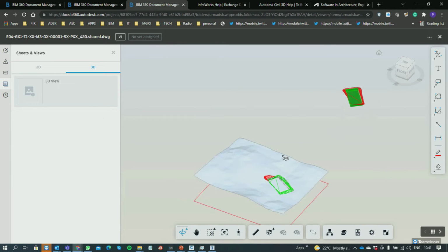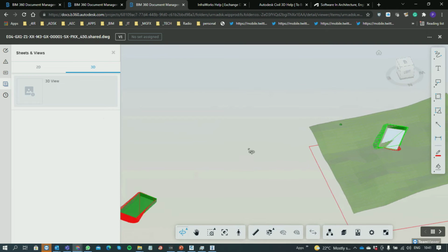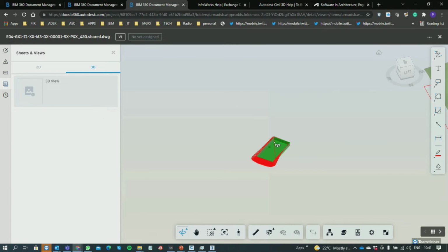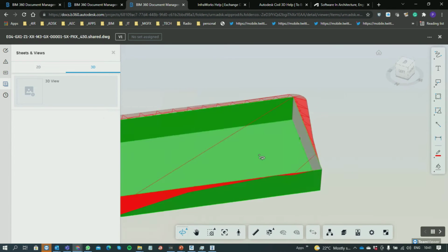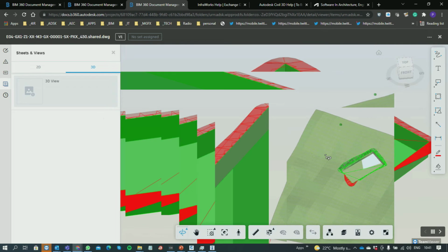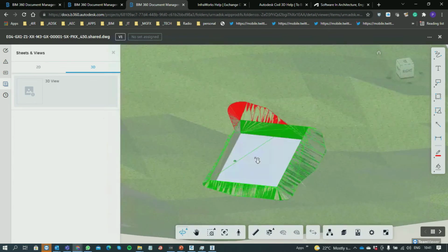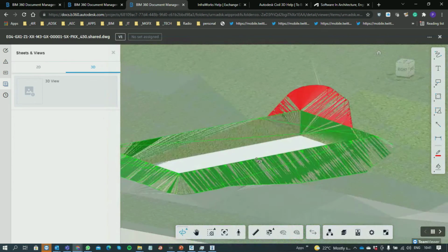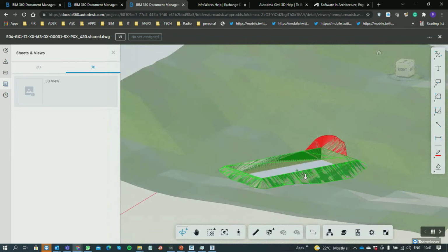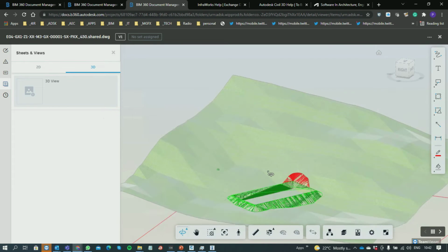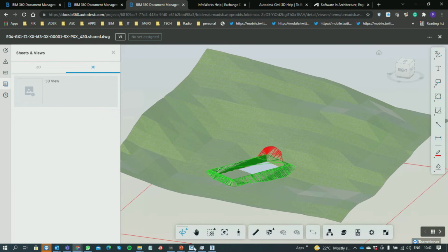Here you can see the surface that was brought out. I've unfortunately included the other surfaces, grading. So that would be a typical grading preparation for a building, which was then integrated into a surface. That is the surface. And this is the published surface that comes directly from Civil 3D and which you can link directly into Revit, provided that you've shared the coordinate system correctly.